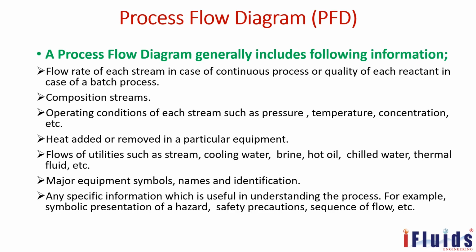Heat added or removed in a particular equipment. If you are using a distillation column or a heat exchanger, how much heat is added, how much heat is removed. In case of coolers, heat is removed. In case of heaters, heat is added. That information we have to capture in the PFD.